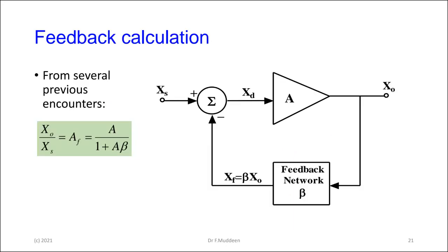And of course, we know how to simplify a block diagram by now, right? You've had quite a bit of experience from that. We know if I give you this with negative feedback, the overall transfer function is A over 1 plus A beta. We are accustomed to doing it with G and H. In this case, we're using A and beta in the nomenclature for this course. So the transfer function of the whole feedback network is A over 1 plus A beta.